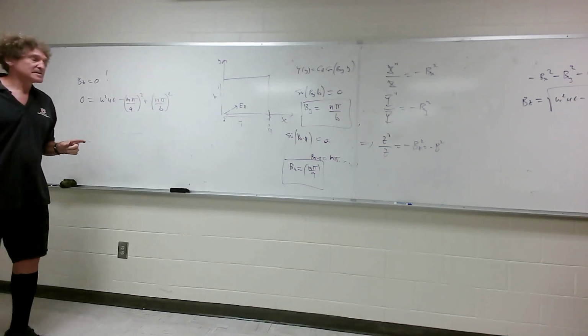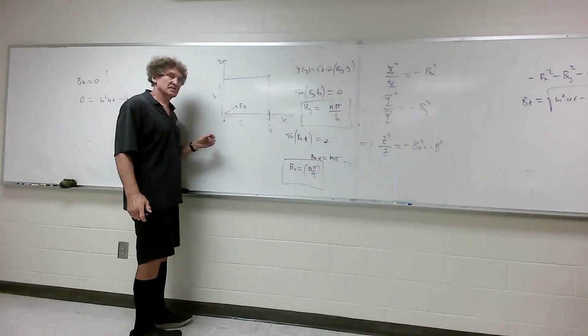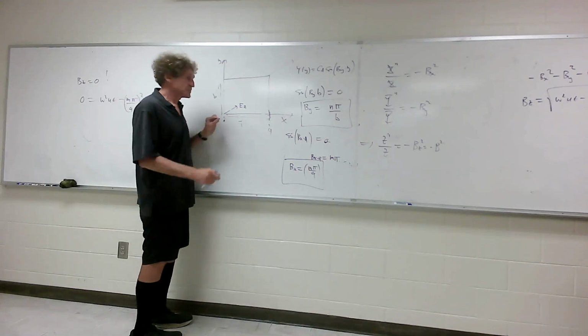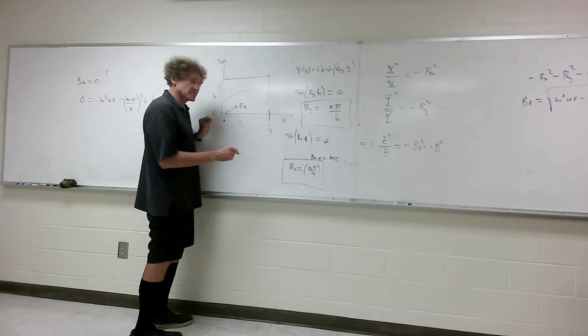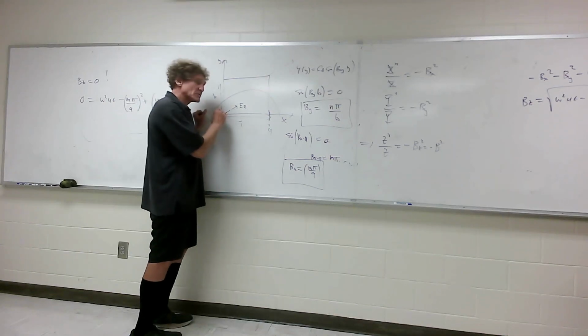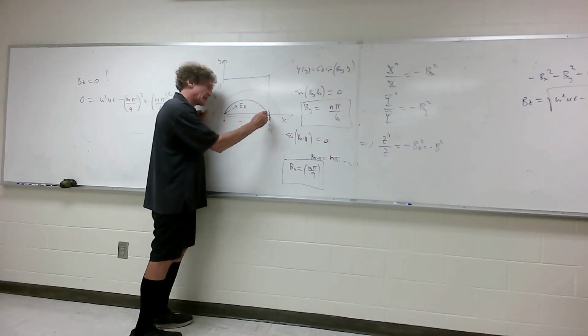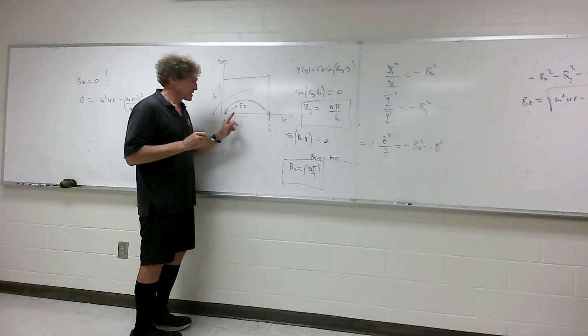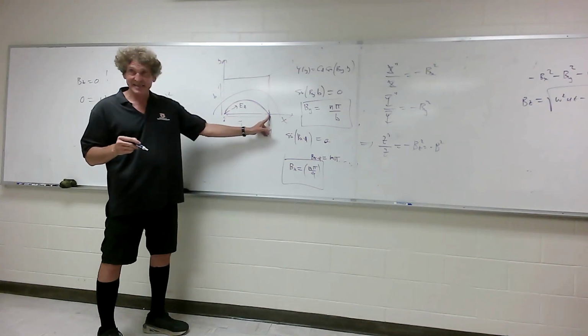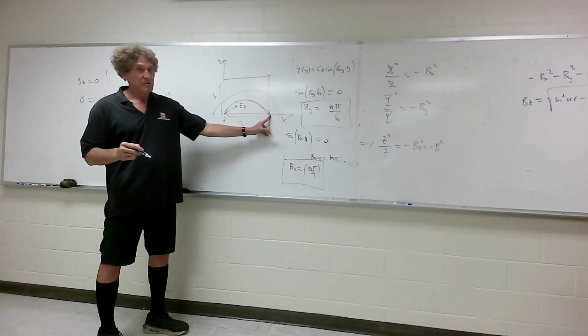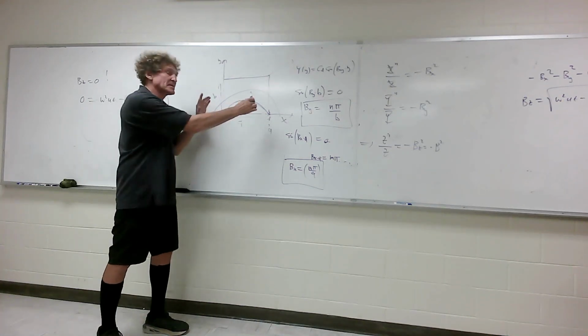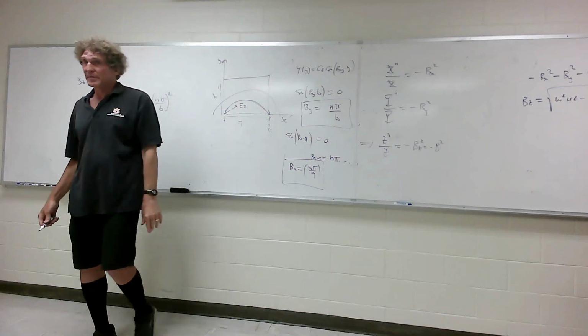And the real reason is, Tom Shumpert was a professor here years ago, he used to say the wave's too fat. If you think about this, this has a sinusoidal variation, right? Well, the lowest order mode we can get here, and you're about to see this, is when this itself is exactly half a wavelength. Any frequency below that will not propagate because it can't meet the boundary conditions no matter what you do. That's the reason.